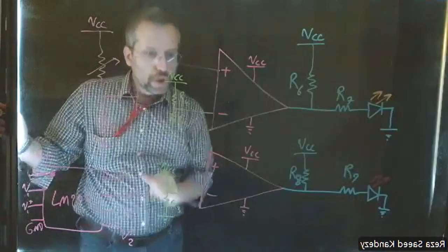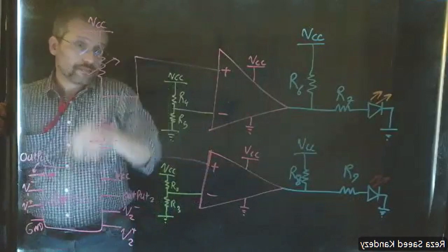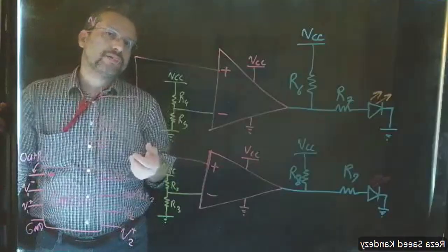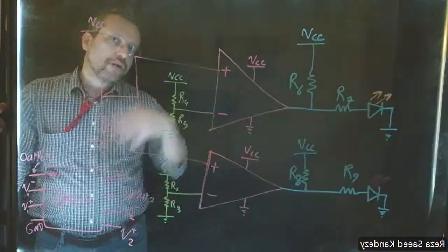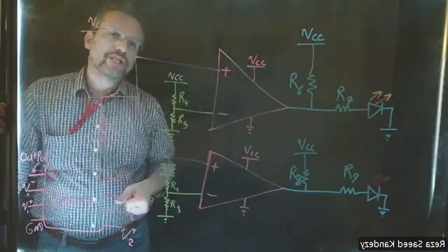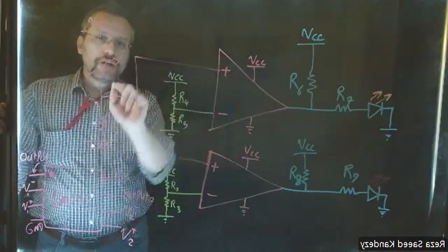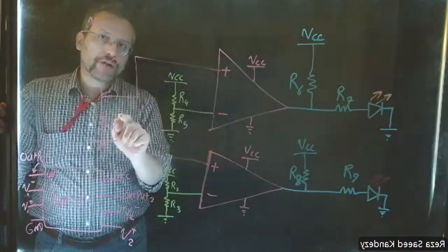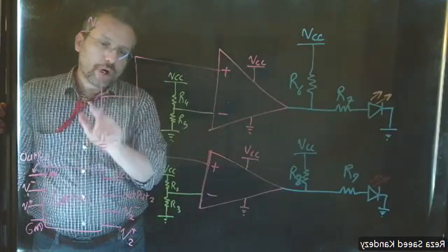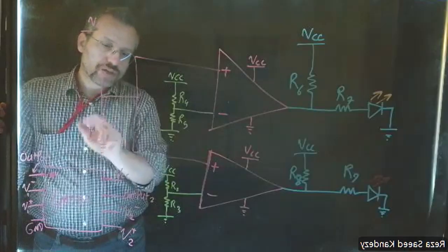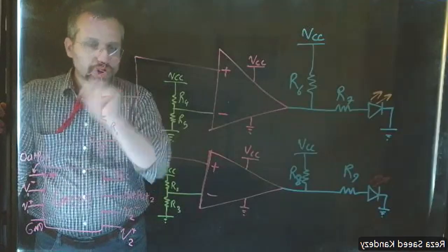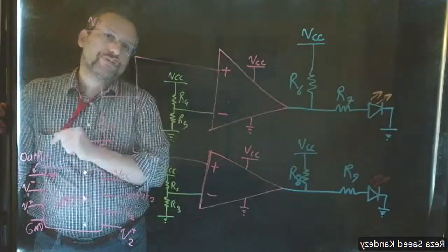Now, let's look at the circuit. In order to translate that temperature into an electrical signal, more specifically a voltage, we need to use a voltage divider between VCC and ground, which divides the voltage between a constant resistor, we call it here R1, and that changing resistor, which is our thermistor.